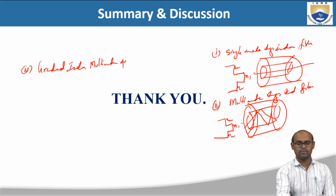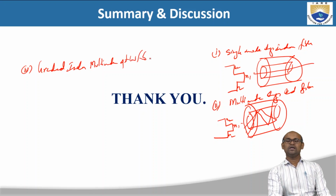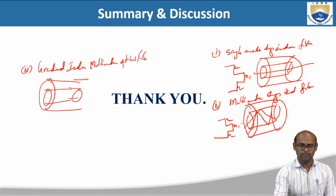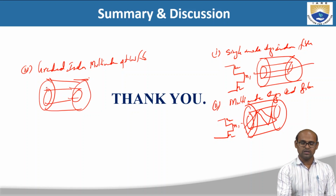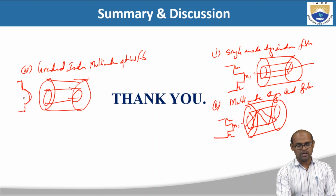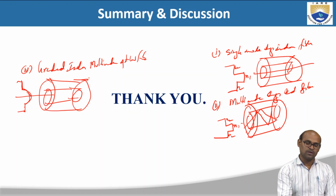In graded index multi-mode optical fiber, we have discussed the structure of the optical fiber. You have a core and you have a cladding, right? Here the refractive index profile is not constant in the core. This is the refractive index of the core, and this is the refractive index of the cladding. The refractive index is maximum along the axis of the fiber and decreases smoothly towards the core cladding boundary.